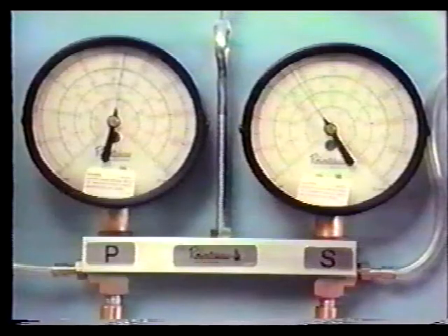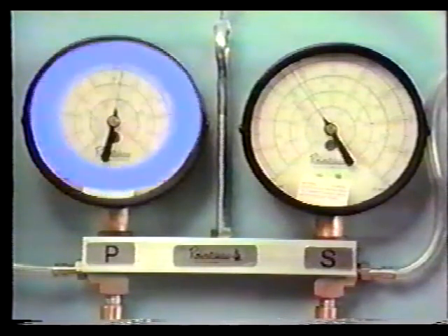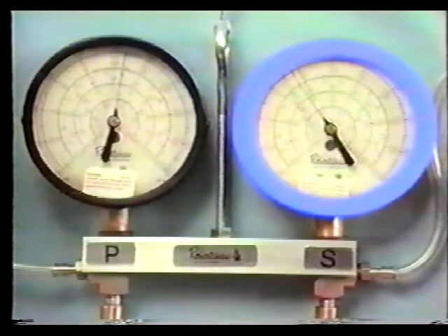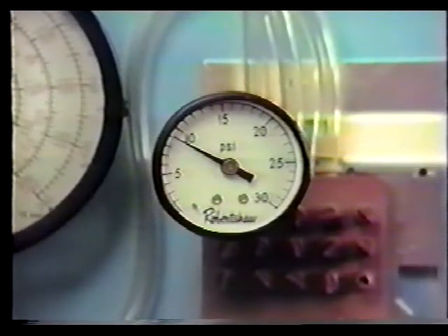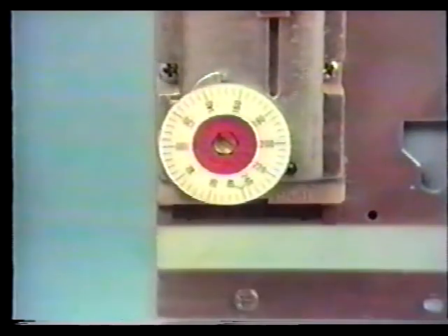Set the primary and secondary inputs to the midpoint of the reset schedule. The primary is set to 150 degrees, reading on the plus 40 to 240 degree scale, and the secondary to 30 degrees on the minus 25 to 125 degree scale. Adjust the control point adjustment to get a 9 psig branch line output. Lift and rotate the control point scale to 150 degrees, or 9.6 psig. This represents the input from the primary transmitter.